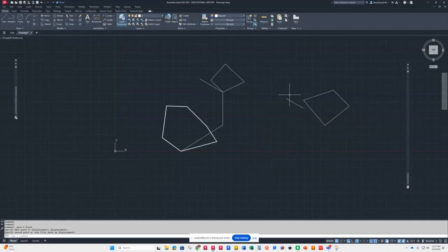You can use your polar, like if you pick that, go to move, and you pick a starting point, and you want to go down at a 210-degree angle, you can do that. And you type in, let's say you wanted it to go 15 in that direction. And that's using polar, with polar on. So those are some things that you can do. All right, so that's move.